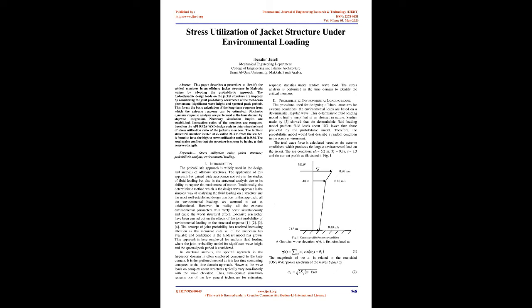This forms the basic calculation of the long-term response from which the extreme response can be estimated. Stochastic dynamic response analyses are performed in the time domain by stepwise integration. Necessary simulation lengths are established. Interaction ratios of the members are computed based on the API RP2A-WSD design code to determine the level of stress utilization ratio of the jacket's members.